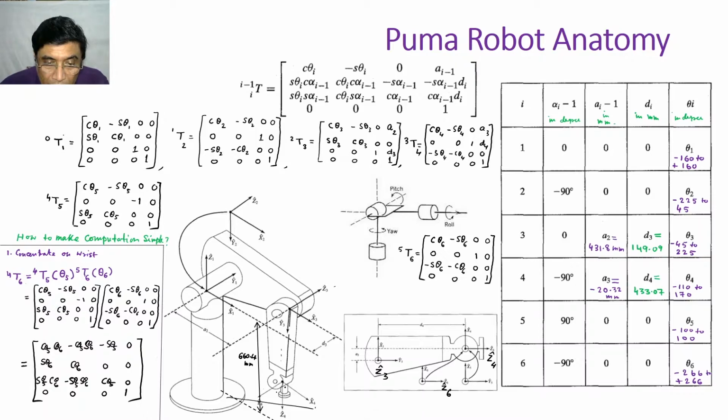You see, only this part will rotate. So this will rotate. And this is called yaw motion, when Z5 rotates, then the entire assembly will rotate up and down. And when Z4 rotates, this is the joint, so the entire assembly will rotate like this. So these are the three motions which have been embedded at the PUMA wrist, and that's the beauty.